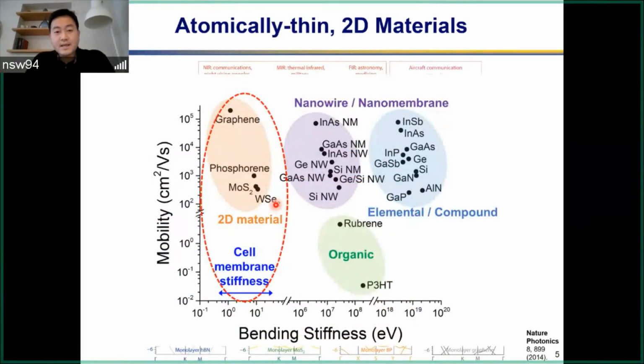Some of the interests as we think about this kind of 2D material and think about some of the features that this material can provide us with. This is one chart I think is quite interesting, and it puts things in perspective, right, in terms of how the impact of thinness plays in lots of things we do. So if you look at this particular graph, I'm plotting the field effect mobility. So this is, right, carrier velocity, carrier transport in a given electric field of a material.